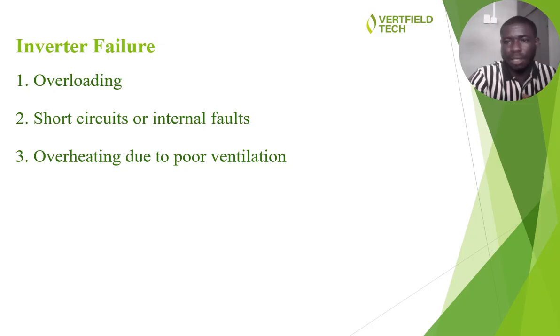Inverter failure. Yes, inverter failure. Your inverters could fail due to overloading when it is powering what is not supposed to power up. Take for instance again your 500 watt solar generator, which is supposed to power up just your laptop, your bulbs, and maybe your phones, right?